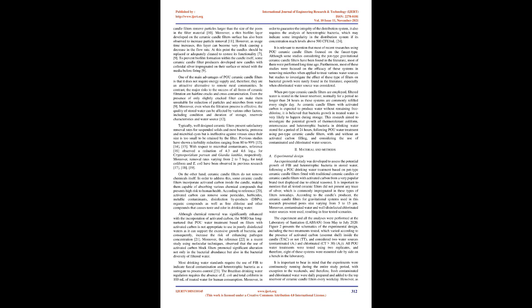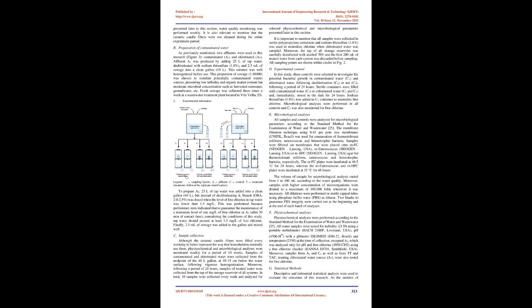It is important to bear in mind that the experiments were continuously running during the entire study period, with the exception of the weekends, and therefore, fresh contaminated and chlorinated water were prepared daily and added to the top reservoir of the ceramic candle filters every weekday. However, as presented later in the section, water quality monitoring was performed weekly. It is also relevant to mention that the ceramic candle filters were not cleaned during the entire experiment period.